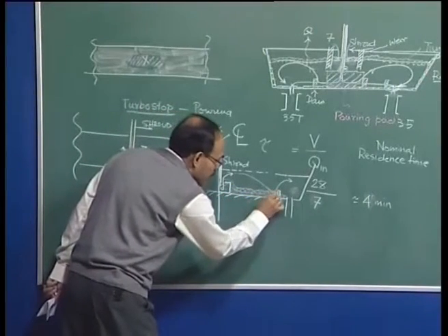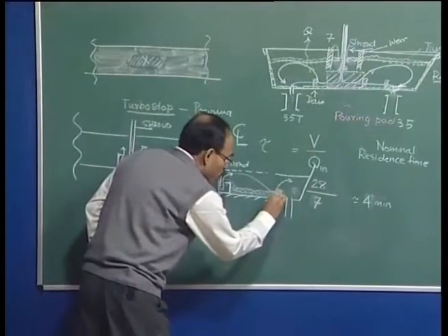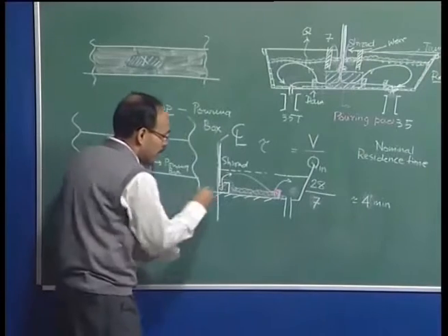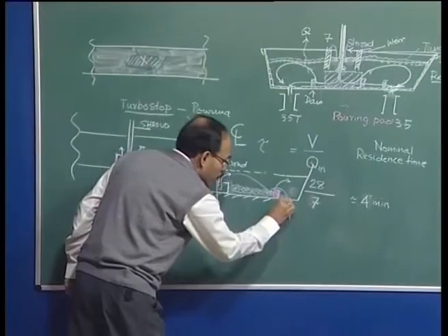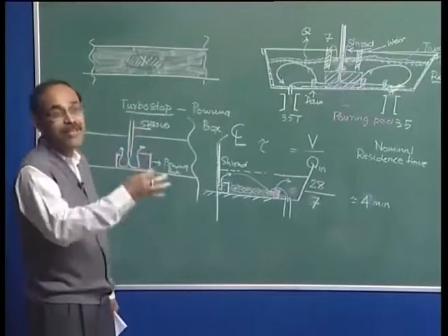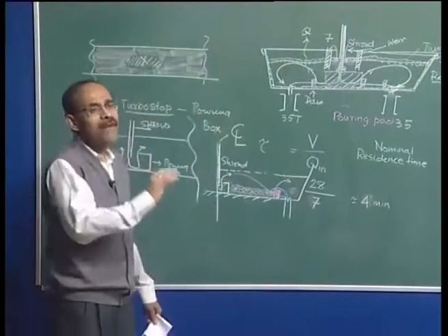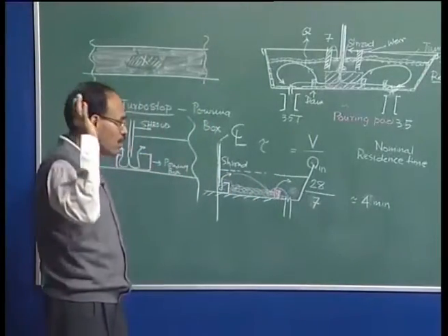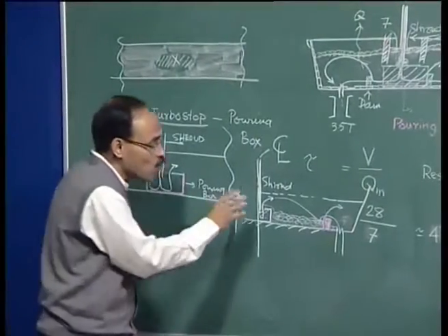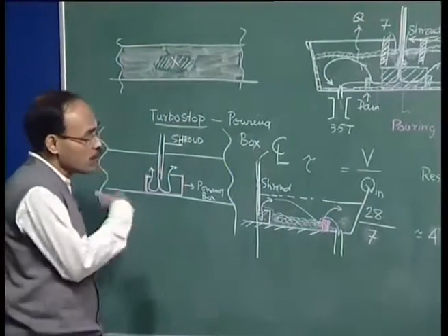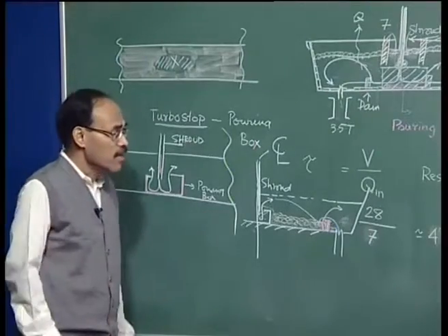If the dam is there, in that case material will not flow, but will keep on piling here, a lot of material, and there will be no freezing, and then at one point of time the material will start to flow. This is the initial stage of tundish filling, that is what I am trying to say. So, the near strand dam has no function once the tundish starts to work. It has a function only in the initial stages, when we do not want any strand freezing because of substantial heat loss from the initial amount of metal which enters the tundish.